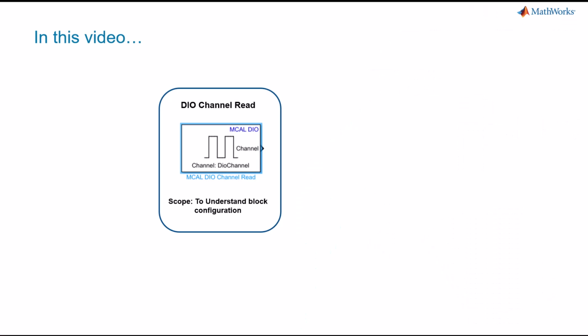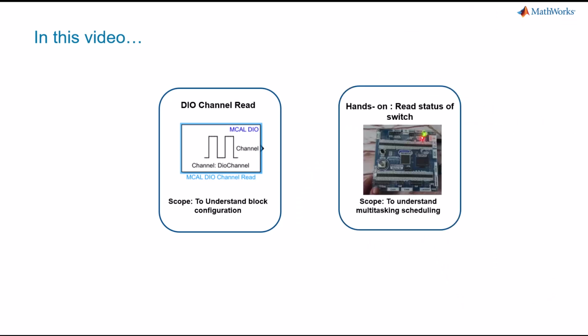In this video, let's focus on the digital channel read block in Simulink and show you how to read the status of the switch and change the LED blinking rate each time a rising edge is detected. Through this demo, the user will have a clear understanding of scheduling and configurations to enable multitasking, along with how to properly configure the digital channel read block.